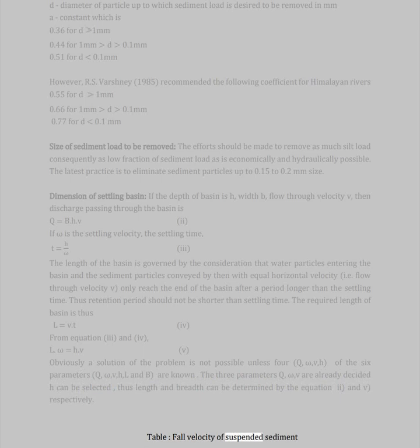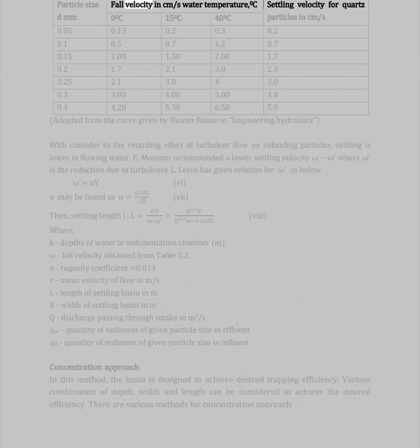Table: fall velocity of suspended sediment. Particle size d in mm, fall velocity in cm/s, at water temperatures 0°C, 15°C and 40°C, settling velocity for quartz particles in cm/s, adopted from the curve given by Hunter Rouse in Engineering Hydraulics.